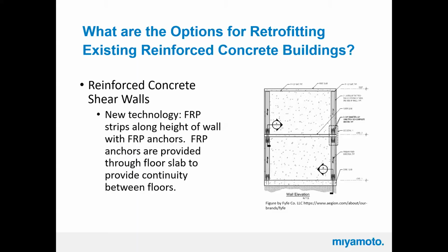You're not going to get any ductility out of the fiber wrap itself, but from the connection between the concrete and the FRP, like the glue, you're going to get debonding there, and that's where you get some of your ductility. It's not going to be nearly as good as a piece of steel would, though. Yep, there are many tools, is all I'm going to say. But these are options. So check with your local jurisdiction and all your local requirements.